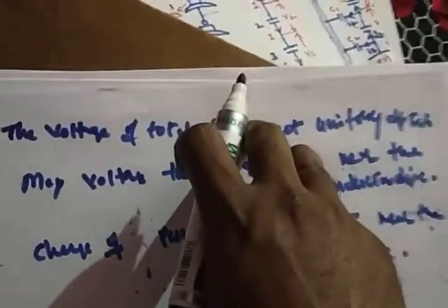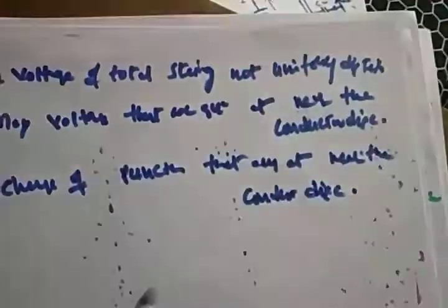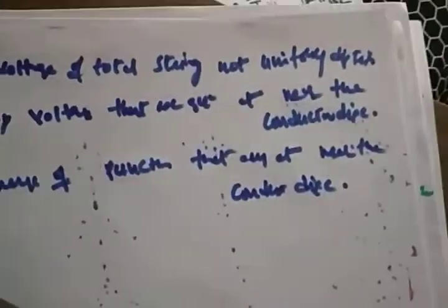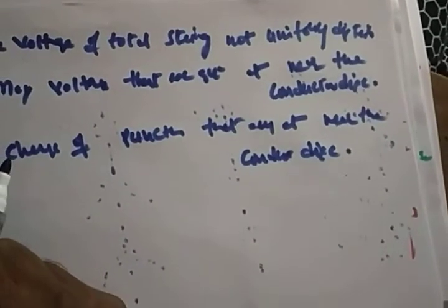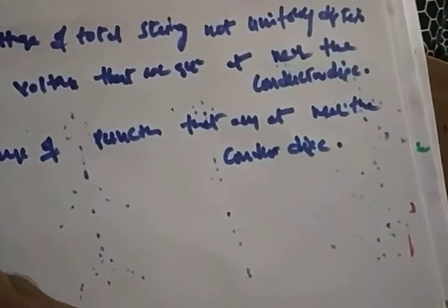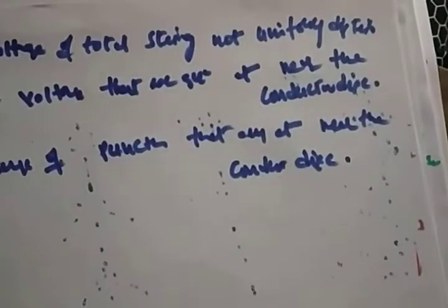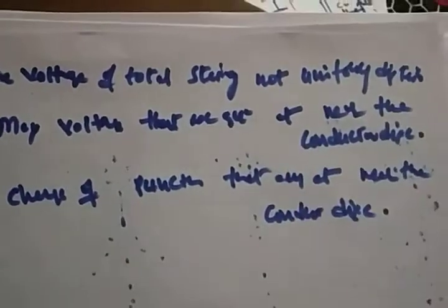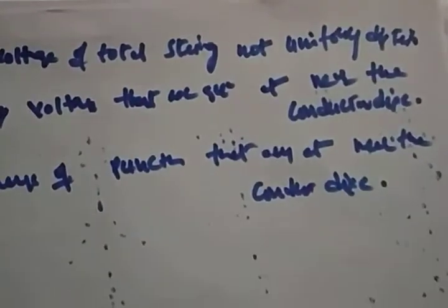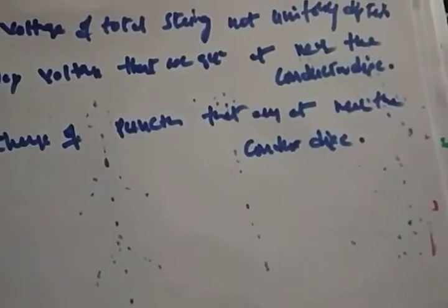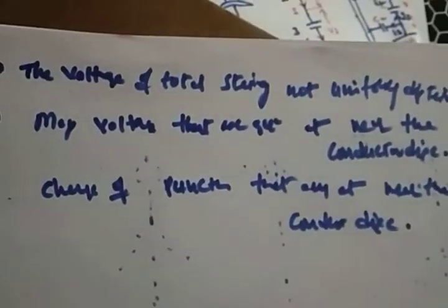So these are the points that we get from the suspension type insulator. How should we avoid this? How should we make all the discs equal potential, uniformly distributed? That can be described with the help of string efficiency. We need to take care of string efficiency in this type of suspension insulator in order to overcome these unequal voltage distributions. Right? So this is about this session.